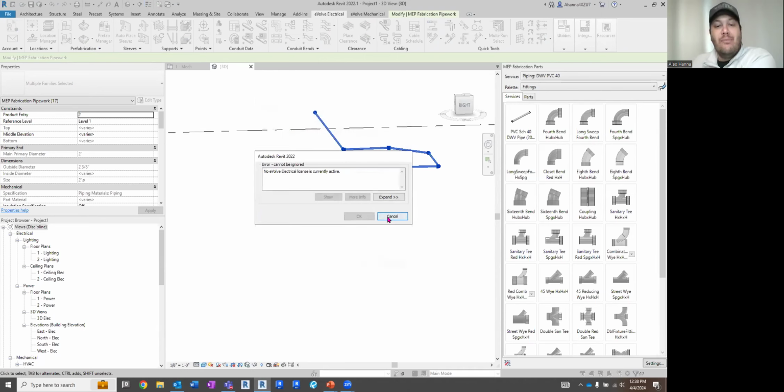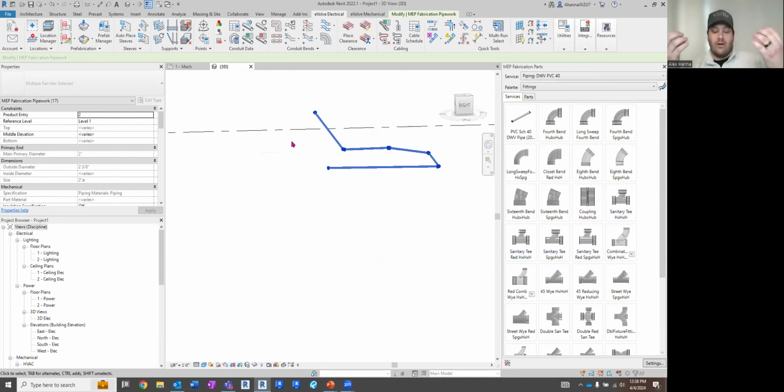No, I'm sorry. But under your Prefab Manager, there are buttons at the top where you select your assemblies. Then you can hit spool assemblies or renumber assemblies. Typically, as a workflow, I have to always hit renumber before I hit spool. Once they're spooled, you'll see the sheets generate.